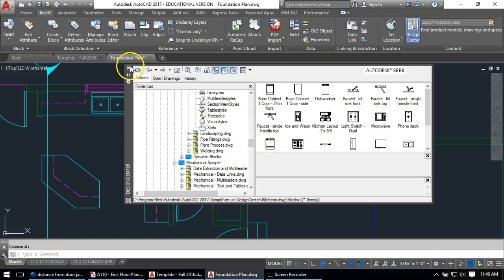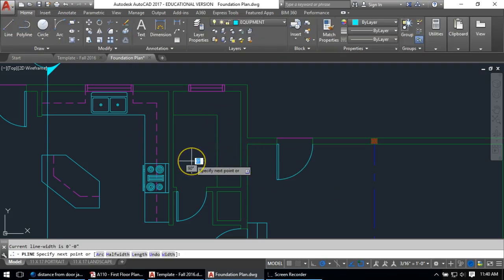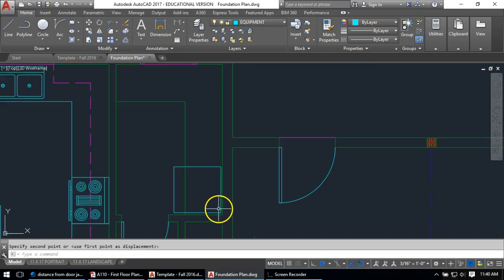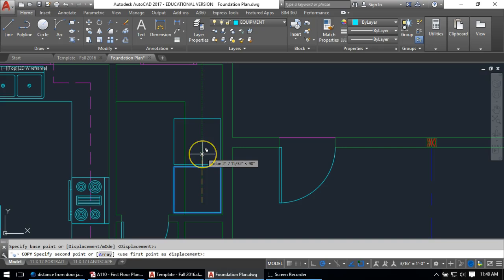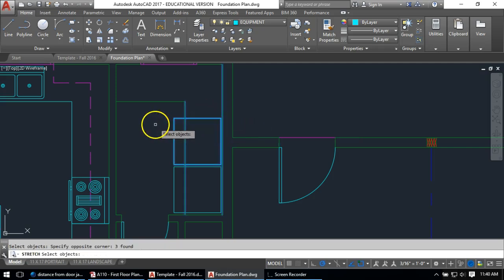Yeah, so I don't see it. So I'm gonna sketch out on my layer. I'm gonna do a polyline and say that they are 2 foot 6, or 30 inches by 30 inches. Same number each, just square. And they're going to be identical. So I'm going to move this just off the corner and just eyeball it up a little bit. I'm going to copy this up here, and then I can sort of see there's a little wing. Looks like I'm going to be a little short at 2 foot 6 because that's only 11 inches coming down. We clearly have more. So maybe these things should only be 2 foot 3 inches.